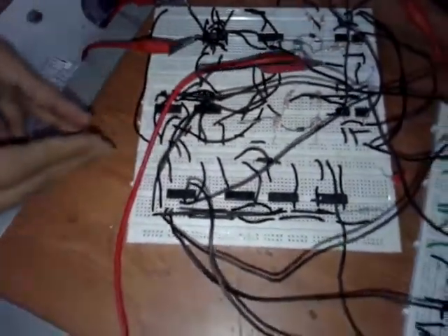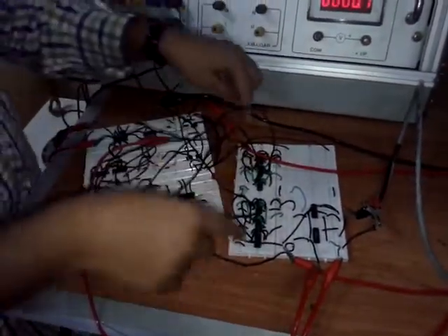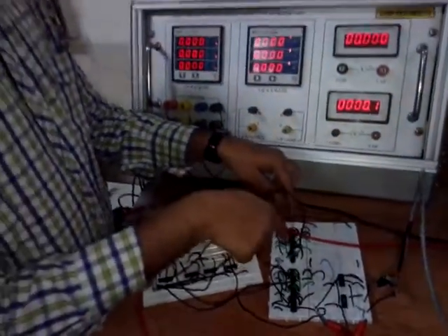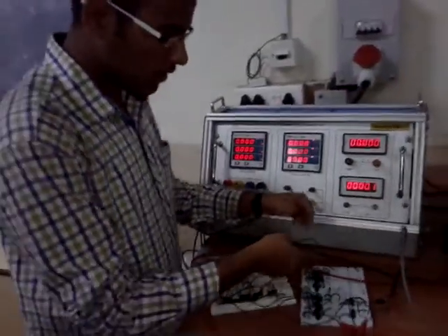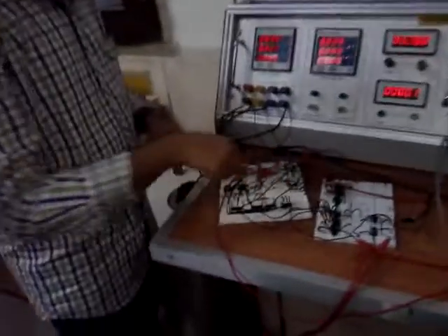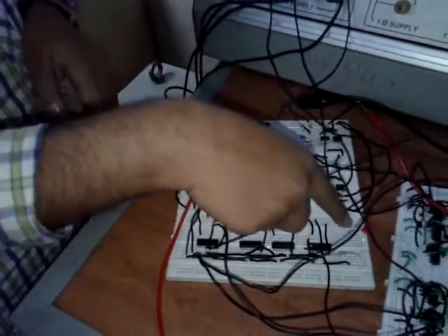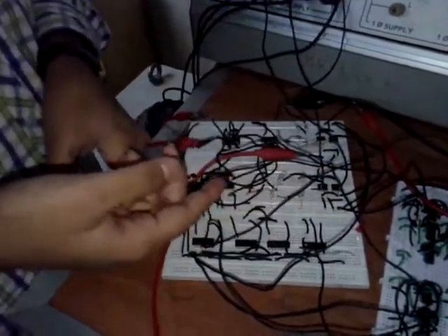Then according to the multiplexers, the data is fed to the 6-bit shift registers located over here. These 3 ICs give the first 6-bit shift register, and these 3 give the second shift register. And over here there is the comparator circuit which gives the final output. Here the LED displays whether the sequence is the same or not.